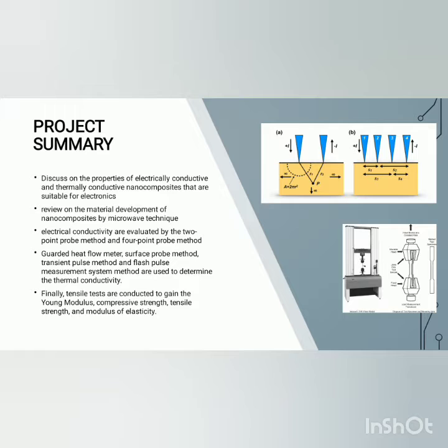Meanwhile, to determine the thermal conductivity, we will be using the guarded heat flow meter, surface probe method, transient pulse method, and flash pulse measurement system method. And finally, tensile tests are conducted to gain the Young's modulus, compressive strength, tensile strength, and modulus of elasticity. Simply to say, the tensile test is to get the mechanical property of the said nanocomposite.